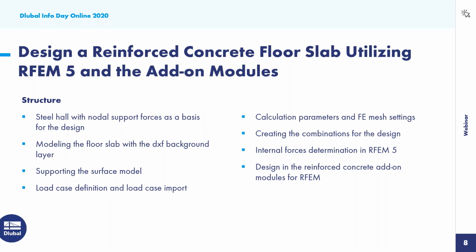I will tell you about the possibilities to define or optimize your FE mesh settings. Then we will create load combinations or result combinations for the determination of the internal forces and later for the design. And of course, at the end of this presentation, we will switch to the add-on RF-CONCRETE Surfaces and determine the reinforcement which is required for this foundation slab.